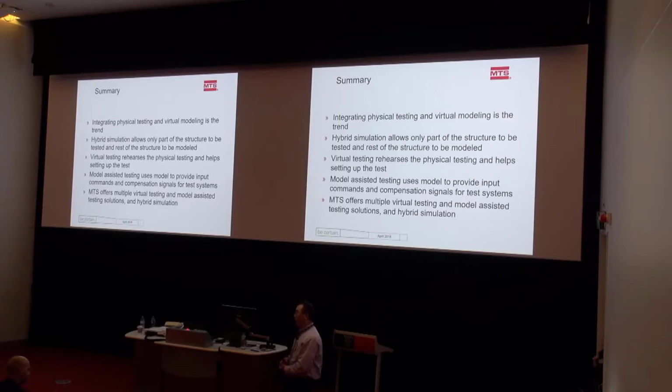In the ground vehicle, we use hybrid simulation because there are a lot of active components, like the damper. The damper is not a simple damper. It has an adjustable valve, and that adjustable valve has to get the command from the computer, a vehicle computer. The computer, based upon the road conditions and velocity, generates a command for that damper, and then the damper changes its property accordingly.